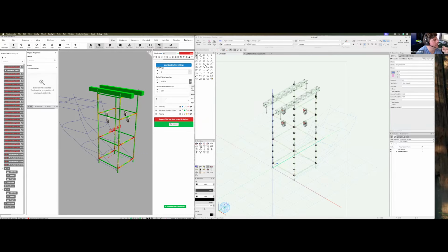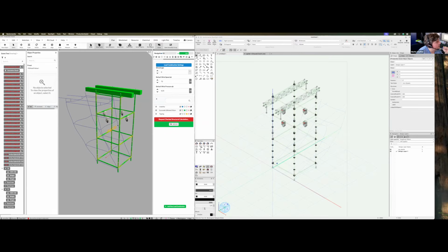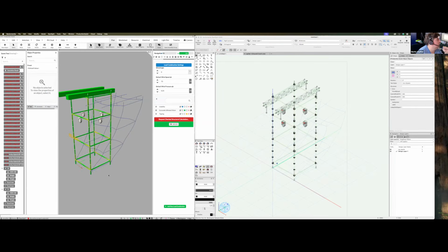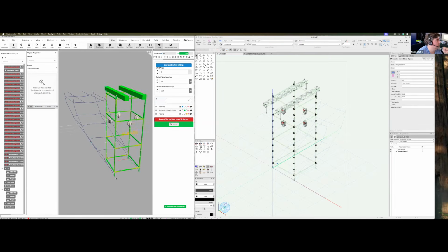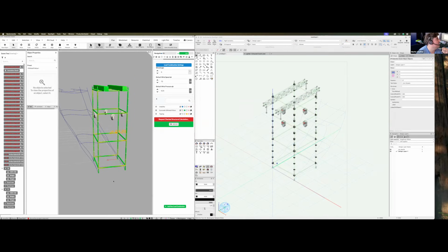For example, a typical thing is that you say, I want to have this at 72 meters per second. If it's 72, the default wind pressure is only 0.25, which would make it okay. So it's not really a good scaffolding, but it would still work. It would actually be okay if you build it like this at that wind speed. So how do I set the correct wind speed?